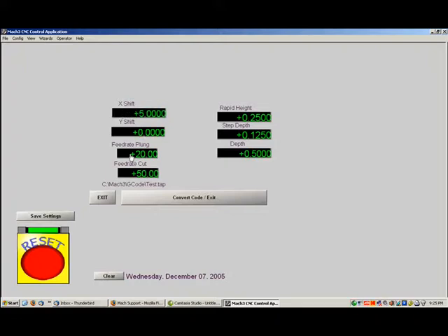shift the Y. The feed rate plunge: any Z negative move, it will put this value on, so your program doesn't even need to have a feed rate associated with any of the moves initially. So if you wanted to type something up by hand, it would just take care of it. We're going to do our in-feed move at 20 inches per minute and our cut at 30.